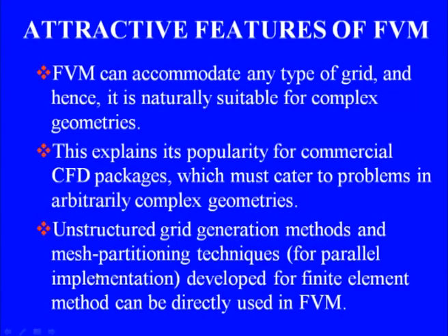And the advances in unstructured grid generation methods have made the application of finite volume to flow problems in arbitrary complex geometries very simple. Similarly, for large scale flow problems which are to be solved on parallel machines, there are geometric mesh partitioning techniques developed for finite element analysis. These can be applied as such to finite volume grids to make a finite volume code run on a parallel machine.